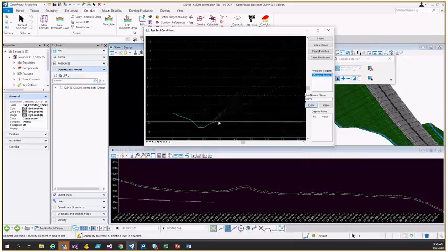As you get to the fixed ditch, it's only set up for one slope. So if you needed a different slope, make sure you change that, and you can use the parametric constraints to change that so that it doesn't break it. But as you change those, don't forget, your ditch width is dependent on the slope. So don't forget about that.